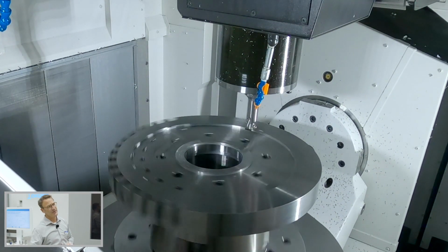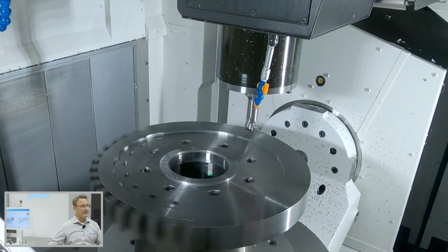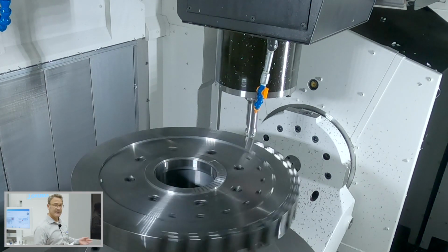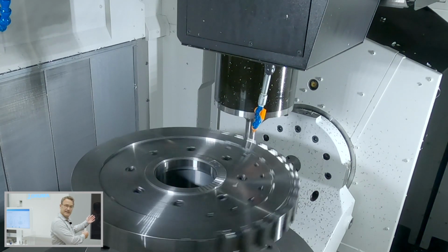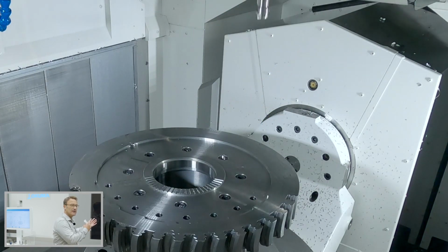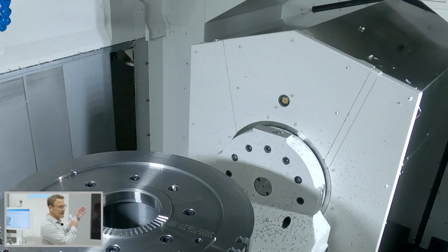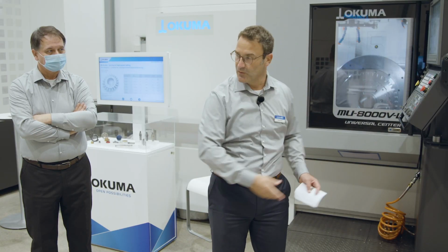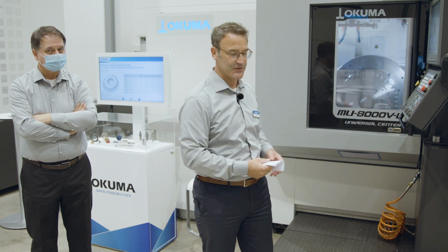We have up to 20 different spindle variations, which the customer can define, whatever he needs. So it's up to your application what spindle we should add to the machine itself. Regarding flexibility, we also have 32 tools as a standard. We can have up to a 268 matrix magazine, so you have a huge tool storage, and it's much better to have these tools in the machine than somewhere in a cartridge, with the operator saying, oh, I need a tool, and running off, and the machine doesn't make any chips at all, which doesn't make sense for these machines.